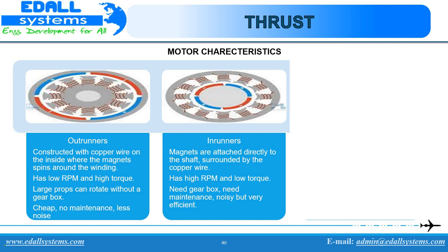An advantage of an outrunner motor compared to an inrunner motor is that the air gap surface is substantially larger. In other words, the surface area through which the electromagnetic field lines pass from rotor to stator is much larger. This way, more electromechanical force is generated.